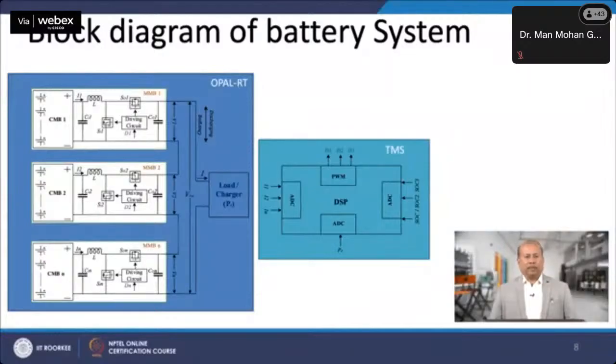3 battery currents are compared with reference currents generated from the algorithm. The SOC balancing algorithm is developed based on the average standard deviations. By comparing the SOC values with the mean values, a balancing factor is determined for all the 3 batteries in a similar way. Using the balancing factor, the power is shared among the battery module accordingly.